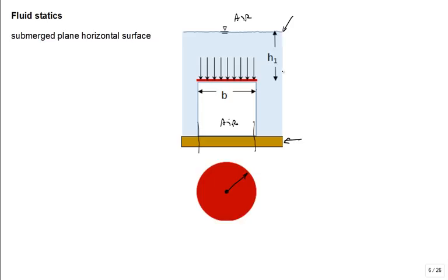It's at a constant depth H1 in the fluid. So everywhere along that lid, it feels the pressure downward from the water pushing down. So what is that uniform magnitude of the pressure on the top of that red circular planar surface, a submerged lid? It's equal to the density of the water times g times H1.